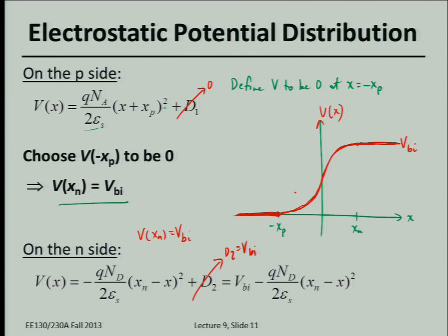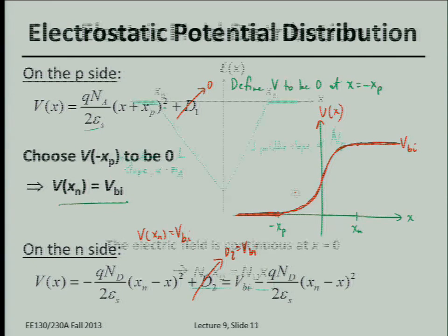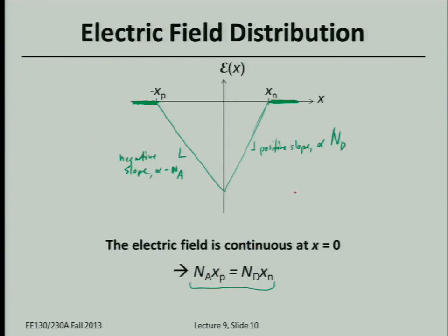Now, for the homework that's due next Thursday, you have to be a little bit careful because, as we'll derive, if the N and P side are not symmetrically doped, if they have different levels of dopant concentration, then because of this equation here, if Na is much, much greater than Nd, then Xp will be much, much smaller than Xn.